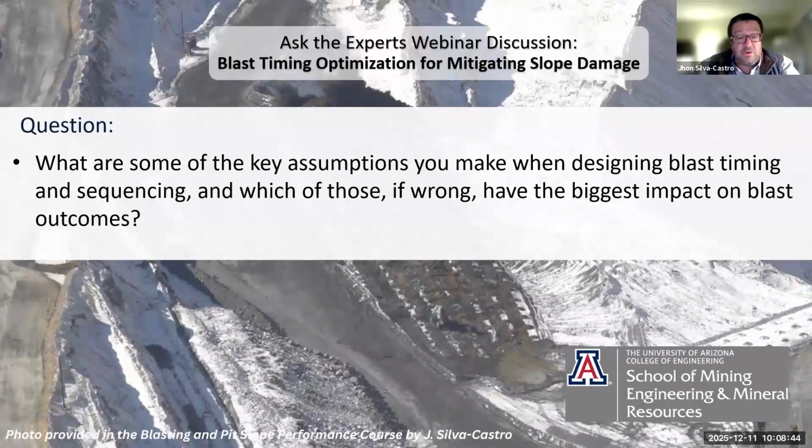sequencing needs to play a role. And usually the main objective of the sequencing is, like everybody says, shooting to the free face. So you have to take advantage of the free areas of the shot, and that will control things like flyrock or even increase on the vibrations in some cases.